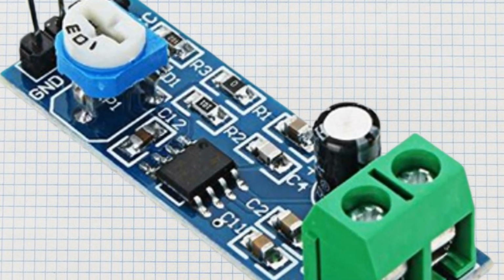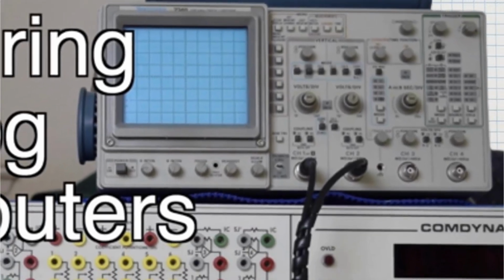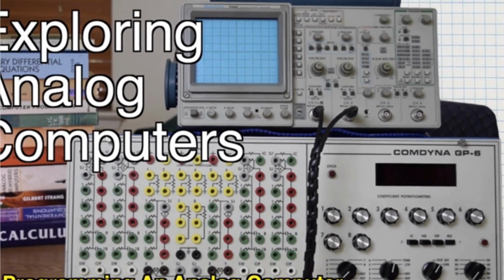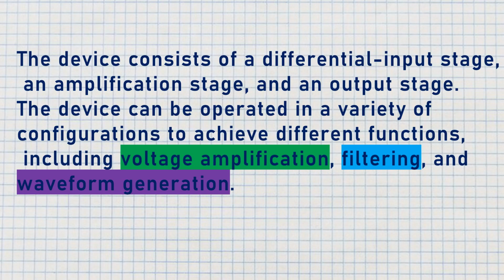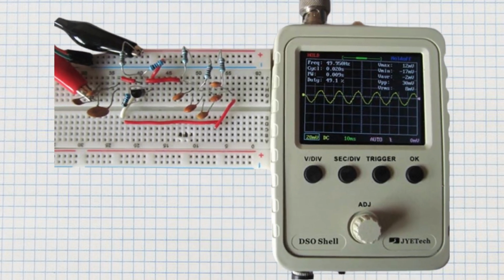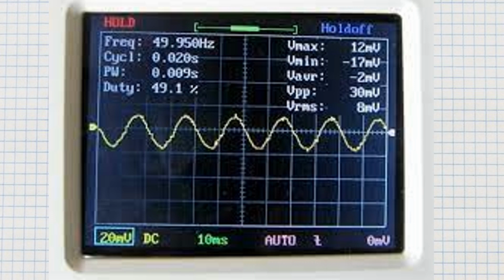The operational amplifier is called so because it has its origins in analog computers and was mainly used to perform mathematical operations. The device consists of a differential input stage, an amplification stage, and an output stage. The device can be operated in a variety of configurations to achieve different functions, including voltage amplification, filtering, and waveform generation. Much like any other amplifier, operational amplifiers offer gain, bandwidth, and noise characteristics to allow them to be used in a variety of applications.